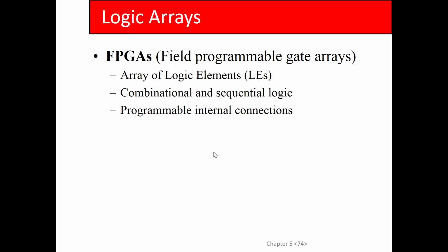Or you can use a programmable logic chip, where you go through some series of steps that take your hardware design and convert it into a form called a bit stream that you can program a programmable chip with, and then from that point on, that chip will behave as though you had sent out your design for fabrication. The only drawback is the FPGA will run about 10 times slower than if you had it fabricated.